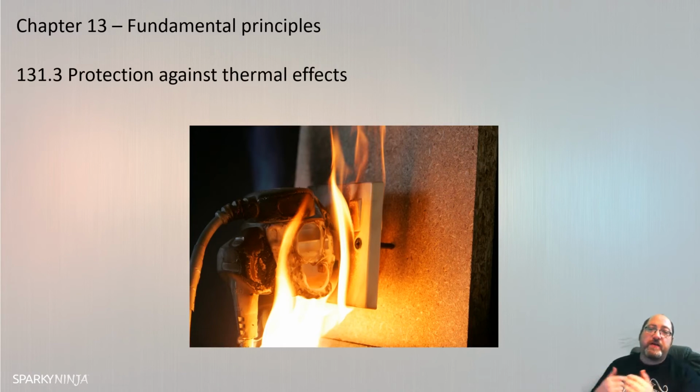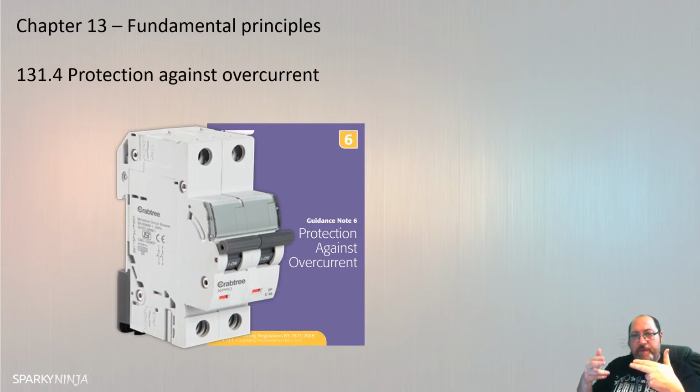We need to consider, when we have a fault condition, we deliberately install a circuit of low impedance to achieve a fault current of high value. The objective of that is the higher the fault current, the shorter the duration, the quicker the fault is cleared.